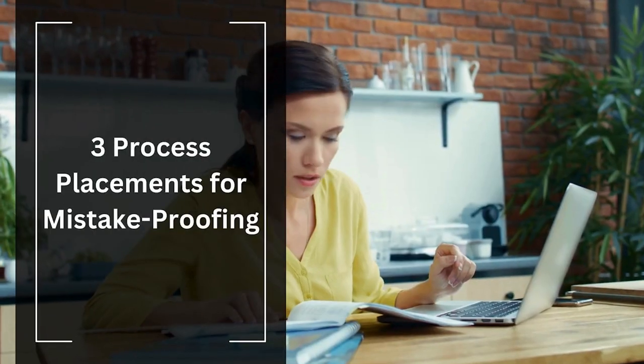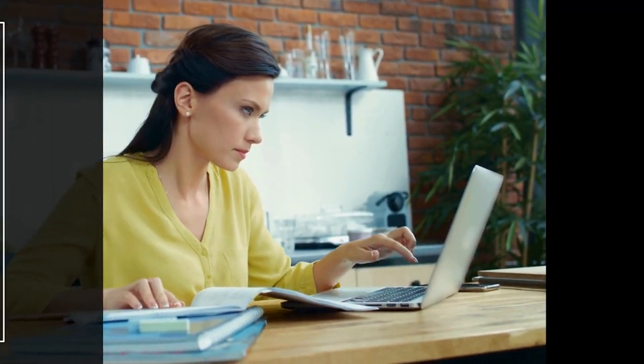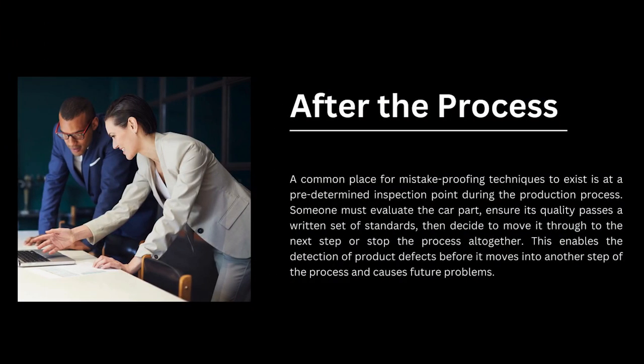Three process placements for mistake proofing. First, after the process. A common place for mistake proofing techniques to exist is at a predetermined inspection point during the production process. Someone must evaluate the car part, ensure its quality passes a written set of standards, then decide to move it through to the next step or stop the process altogether. This enables the detection of product defects before it moves into another step of the process and causes future problems.